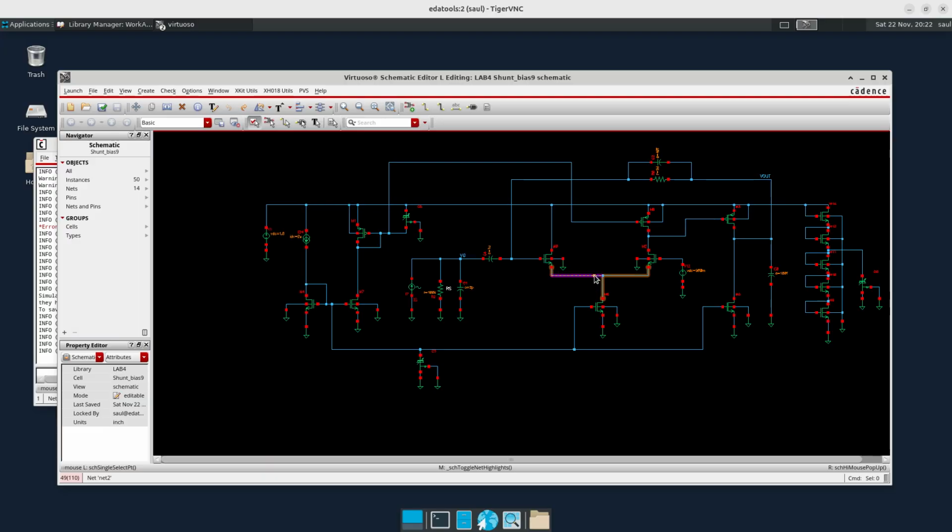differential pair, the sources of the differential pair coming here. The output will be also coupled through the current mirror. Here it is going to be also mirrored back to this point. So I have an unintended feedback that is introduced due to the presence of the current mirrors. And to break these feedback loops that might change the stability and the dynamics of the loops, what I do is I add coupling capacitors.